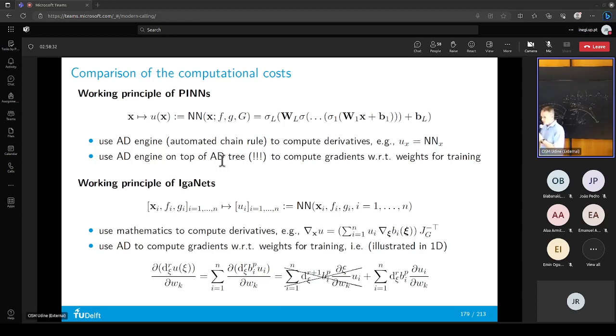It's a little bit crowded, I apologize for that. But what do we have? The network produces the coefficients. What do we do in standard FEM or standard IGA if we want to compute the derivatives of a function which is represented as coefficients times basis, summed over everything? We don't do AD or any fancy stuff. We just say the coefficient is a coefficient and the derivative goes to the basis. So we leave the coefficient as it is and differentiate the basis.